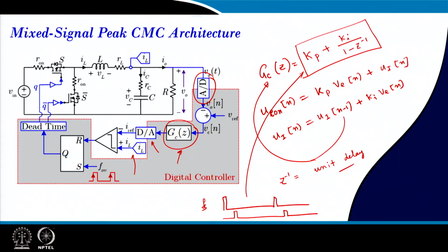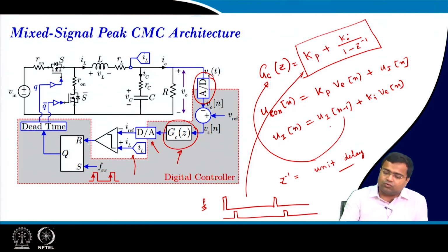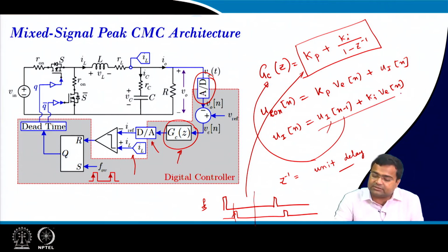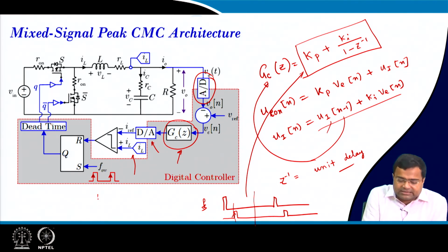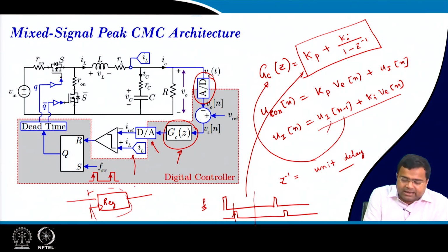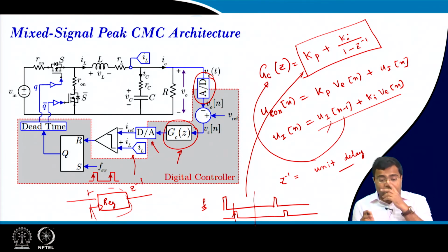So, in summary, if you want to customize that, I want to start computing once the sampling clock is sent to the ADC and the data is ready. Then you have to realize this: basically, this UI[n] will be a register. There will be a clock, and the register will store and pass data, and this register will behave like a Z inverse block.